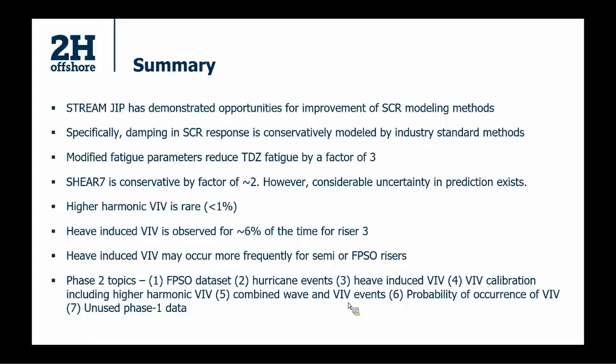Yes, good question again. We are saying that these parameters work for SCRs only right now, because it'll be going beyond our scope. I guess it is too early to say that it's going to work on flexibles as well. But there'll definitely be more damping, and there are usually no strakes on flexible risers, so the entire strake CD concept is kind of moot here. But if there are background currents and you are confident of a particular value, it is recommended to be used.